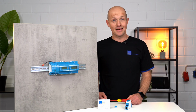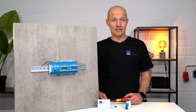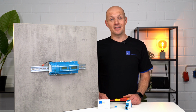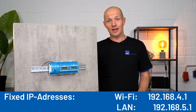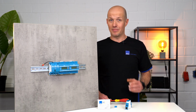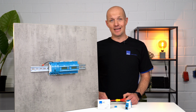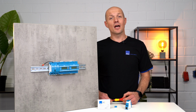Now that we have assigned the device address, we want to integrate the FGW14 into our network. It is important to note that the FGW14 has fixed IP addresses, which may vary depending on the network or Wi-Fi connection. To do this, simply open your browser and enter the IP address of the respective interface. This will take me to the web interface, where I can make various additional configurations.